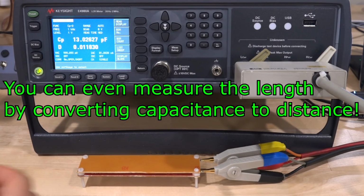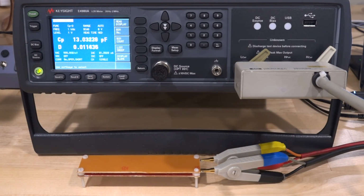We can also try maybe a piece of paper like this one. Here we go. Add that to the middle of this one. It's going to be a much larger effect because it's much bigger, and therefore a wider area of the total capacitance is now covered with a dielectric material that is not air. So that's now at 15.5 picofarad.